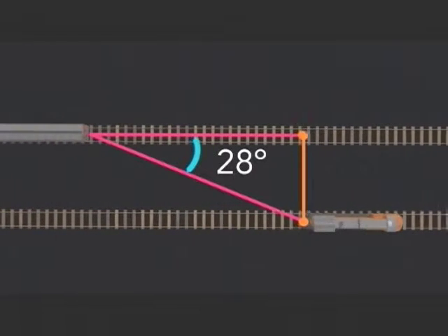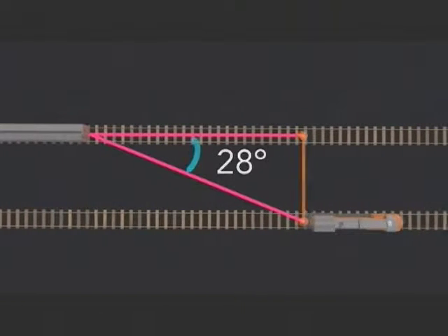Now, if a power triangle is substituted for the train, we can see that the same principle can be used to show the relationship between working and non-working power in an electrical circuit. To do this, let's begin by labeling the angles of the triangle so we can refer to each part clearly. Line AB represents the working power in kilowatts. Line BC represents the non-working inductive power expressed in kilovars. This is the power that has been used to magnetize equipment along the circuit to that point.